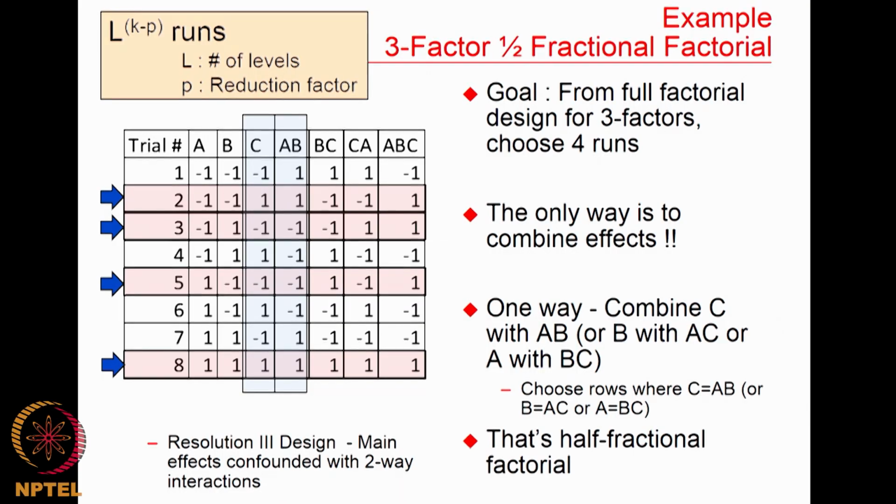So, the one thing that I want to discuss is how do you confound. We saw this in terms of factors, right. But what is actually happening in the L8, in the orthogonal array, when you go from L16 to L8? How can you recreate L8 from L16? What is the physics behind it? Practically not physics, but what is the idea behind it?